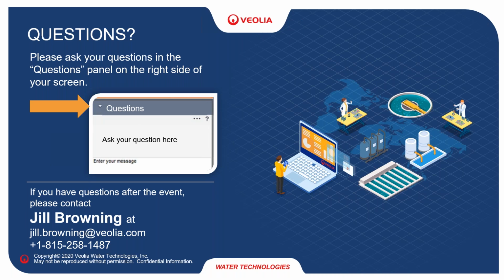Yeah, on that one, while we wait for Oscar, I've got a couple more that have just come in as well. Can this technology be used to reduce benzene to below 10 milligrams per liter? So downstream processes are exempt from BWON. I'm not sure what BWON is, but CoStrip works by taking what's coming in and reducing the concentration. So, for example, I would need to know what the inlet BTEX concentration is, and from there we can say, are we getting an 80% removal, or what is the percentage of removal? So if it falls within that, yeah, we can achieve below 10 ppm of benzene.